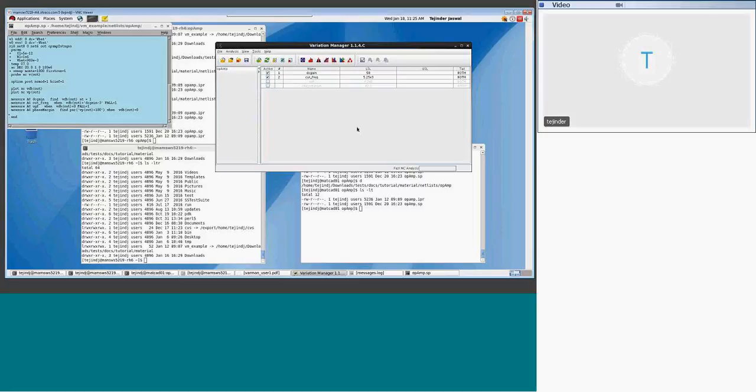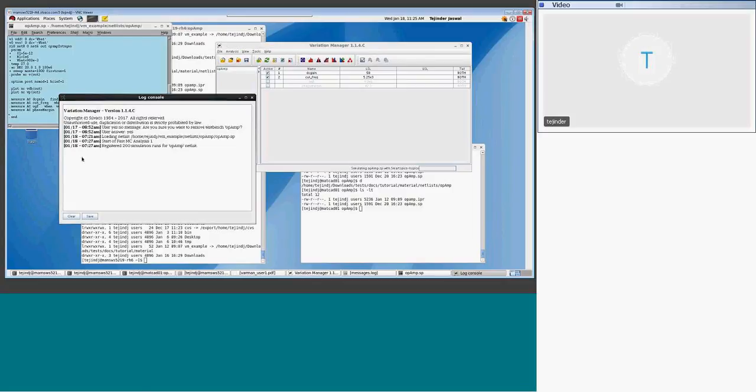So it's going to say fast Monte Carlo. As Firas mentioned, you can start with that because you don't have the design limits yet. It comes under the variability analysis. Then you can enter the parameters specific to your design. While the simulation is running, you can open the console. Here you can see any warnings and errors.